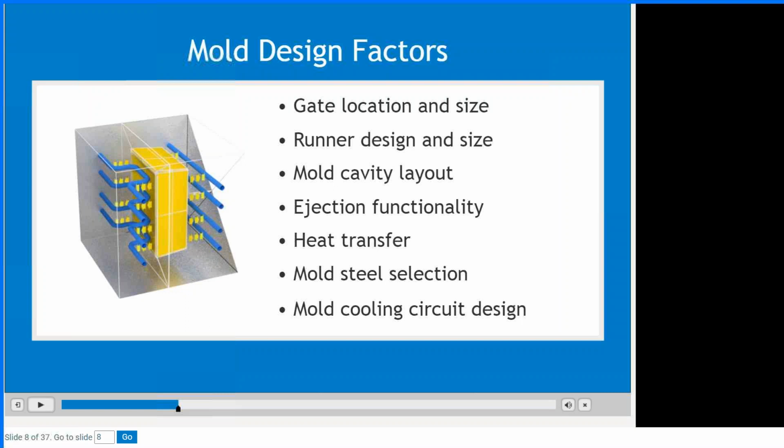If we don't have cooling in the tool, we get a heat trap, which will then cause overheating and all sorts of challenges. So not only the part design is important to optimize, but all of these factors. When you design a mold, be very, very diligent in understanding which components are really important for a smooth operation and to optimize this mold design. Very, very crucial. Okay.